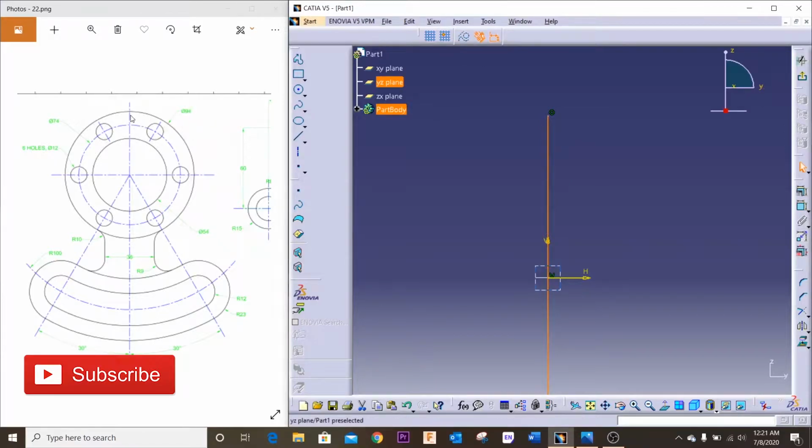and I'm going to make these two concentric circles first. So I'm going to select the circle command. Oh sorry, I think I've turned this off as a construction. Yeah, so now I'm gonna deselect it. I'm gonna select the circle, make a concentric circle.